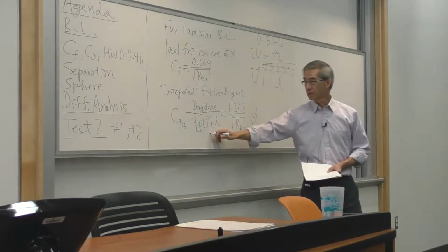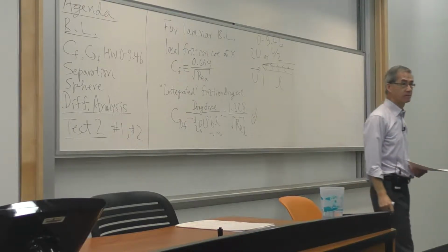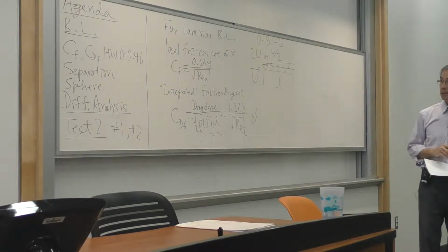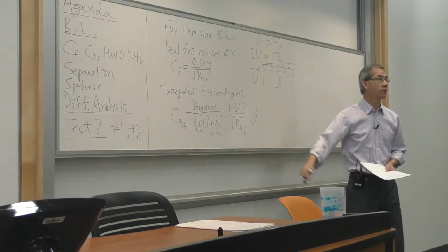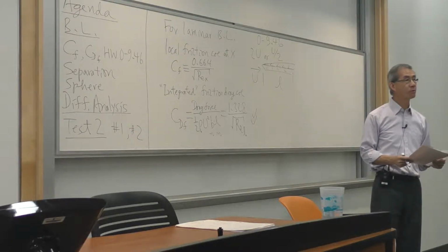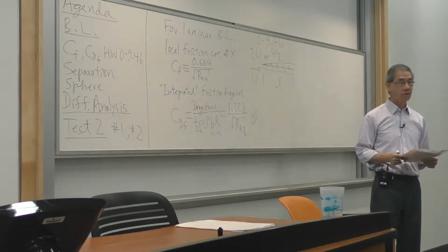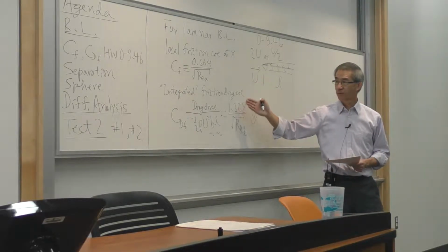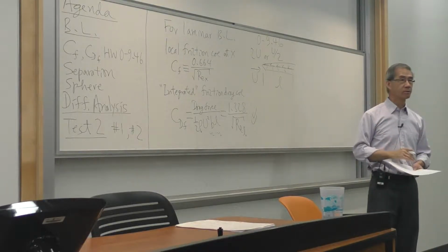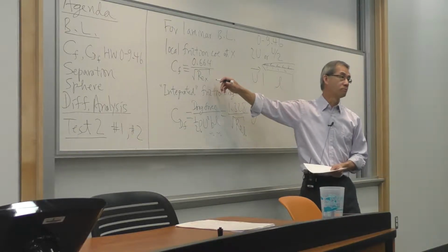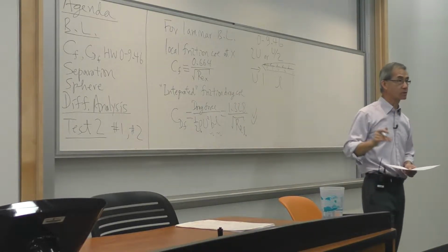And those nomenclature, do you have any question how to use this? This is nothing new, I'm just clarifying some of these concepts that some of you may have. So what happened here when you change the velocity is you're changing the Reynolds number. All right, and the plug-in chug is straightforward and very simple. And the next set of homework, very similar, laminar boundary layer. That's all we have, an analysis and the formulae that we can use. Turbulent is a little different, we'll cover that later. And it's different from this local drag coefficient. Do you see the difference? Do I have to explain that again?